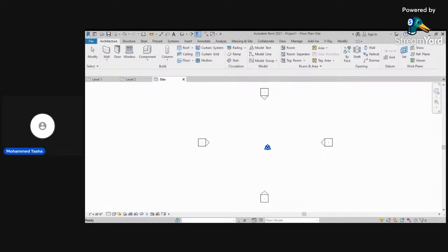Next, you have ceiling plans, where you can see the plan of a ceiling, where the lights are placed, what the design of the ceiling is, and what the level of the ceiling is. This is mainly related to false ceiling, plaster of Paris, or something like PVC ceiling or gypsum ceiling. So these types of ceilings can be viewed with the help of ceiling plans.